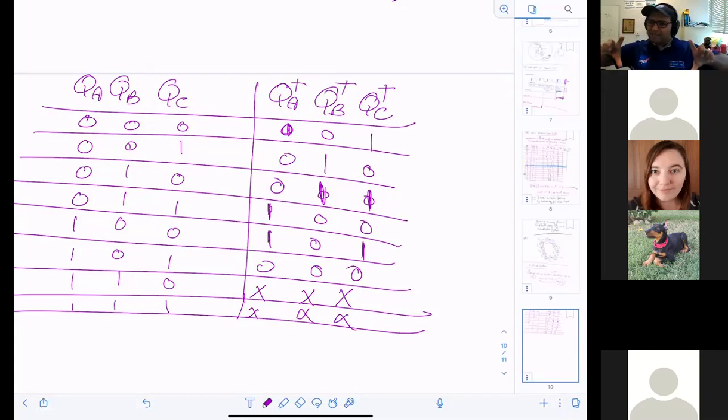Do you remember when we make the K-map, right? When you have a bunch of X's, it's going to make it easy for you. Look, from here there is no way for you to go to even 6 or 7. You're going to go back to 0, and then you will just go like this. So it's better to put X somehow and figure out a way to use it when you generate TA, TB, TC, whatever. Then it will use fewer logic gates for the implementation.